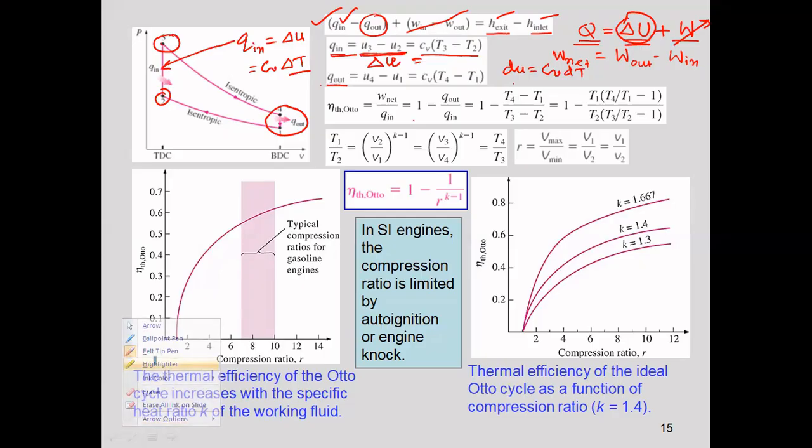In this relation, for 4 to 1, you see, during this process volume is constant. So again W is 0. Therefore it will be Q is equal to delta U. That is, heat transfer is equal to change in internal energy. Now, what is the change in internal energy? It is U4 minus U1.